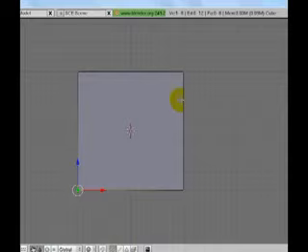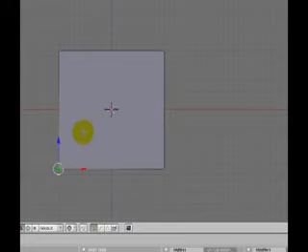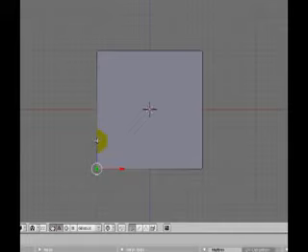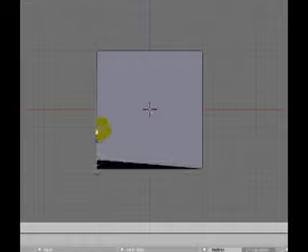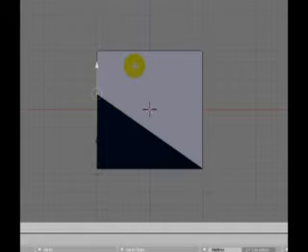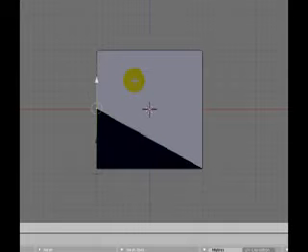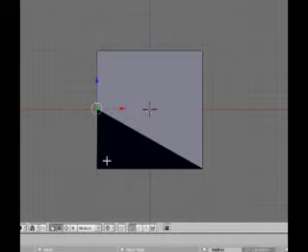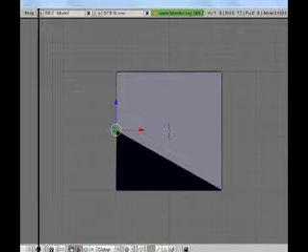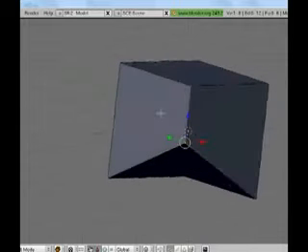So if we move it from the side view and we grab, this is a confusing part, but if you want to grab an arrow, you actually need to use the leftmost button. To select everything in Blender you use right, but for some reason you grab these arrows with left. Maybe it's just so you don't accidentally grab something else, I'm not sure. So you hold in the leftmost button on the arrow you want to move, and you'll see that we've now moved that vertex roughly halfway in the upward direction. Now if we hold the middle mouse button down, you'll see what it did to the shape.